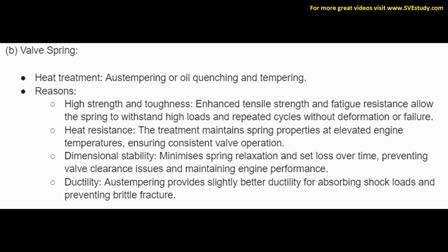Heat resistance. The treatment maintains spring properties at elevated engine temperatures, ensuring consistent valve operation. Dimensional stability. It minimizes spring relaxation and set loss over time, preventing valve clearance issues and maintaining engine performance. Ductility. Austempering provides slightly better ductility for absorbing shock loads and preventing brittle fracture.